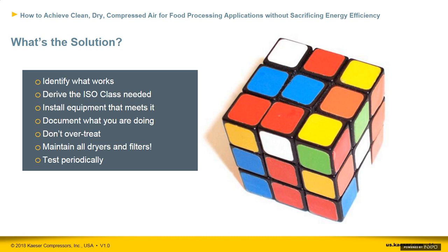In short, there are common practices based on experience, but there are plenty of people buying desiccant dryers and extra filters just because they've been told they're needed, or just to be safe. A key point is that once you pick your specs, be sure to maintain the dryers and filters so they perform to that specification. Now, I'd like to go in more depth on some best practices.